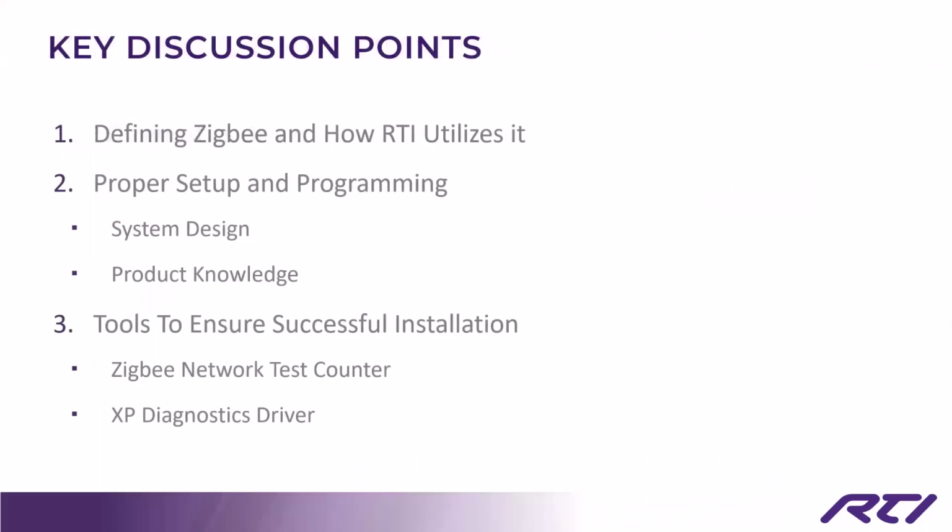So really, Zigbee is an extremely effective communication protocol once set up properly, and is the primary communication method for RTI XP processors and remotes. And we discussed what Zigbee is and how it works, the proper setup and programming method, the tools to be able to utilize the Zigbee network test counter and the XP diagnostics to ensure successful installation.